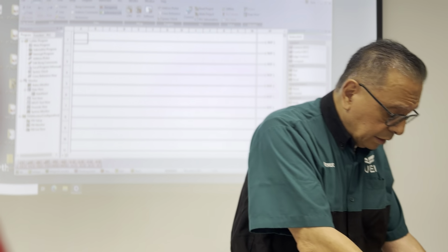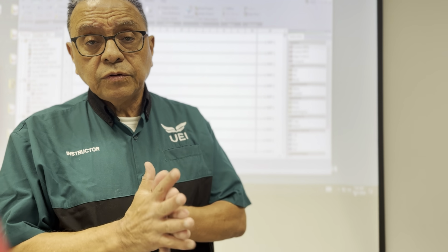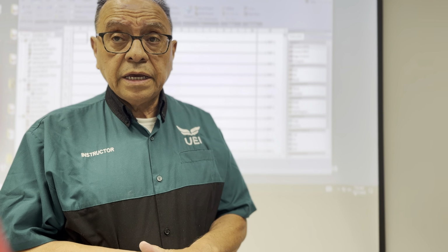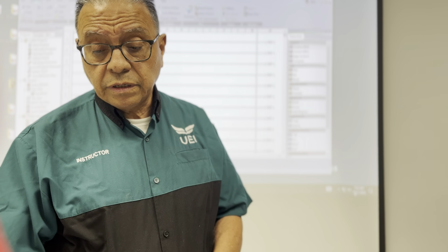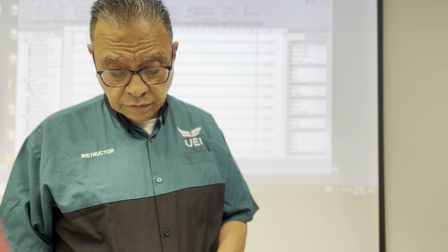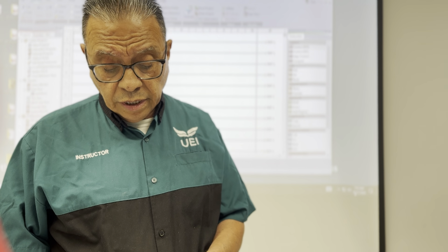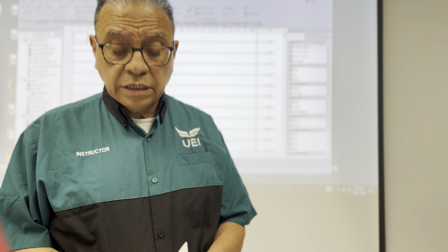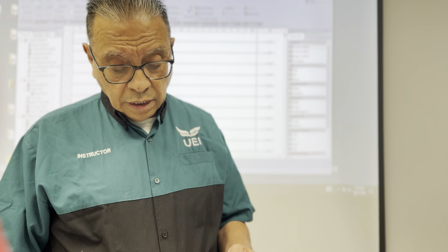And let's start talking about this program, okay? So today we are going to be testing several scenarios, okay? We are going to be using some conditions: the typical condition, unconditioned or condition, exclusive or, and also non-retentive latch. Typical use on electrical motor control.